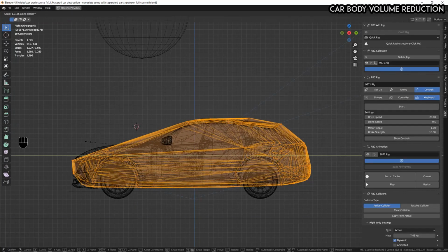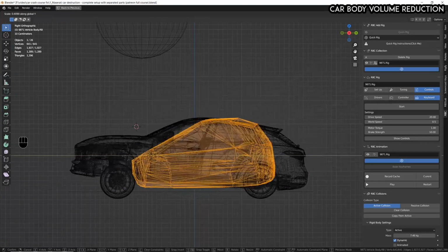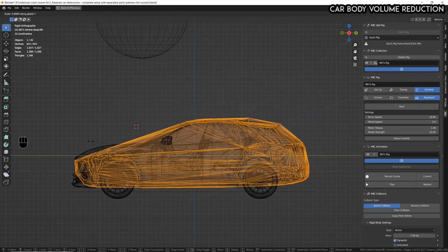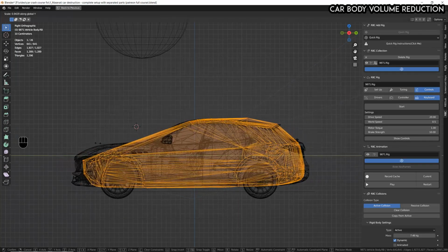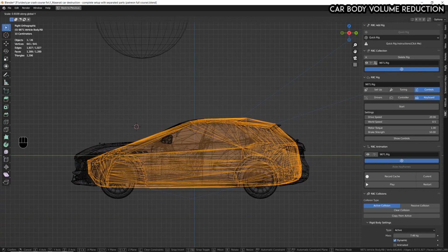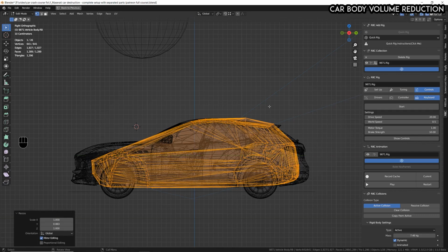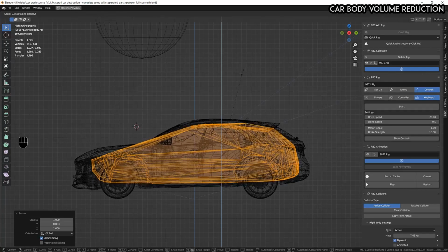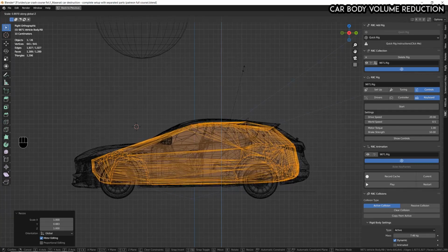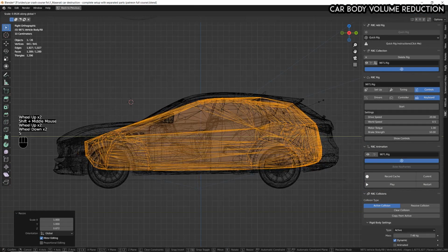Basically, I want to reduce the size of the rigid body a little bit like this. You will notice that the car is starting to rotate with all the parts as well. Don't worry about that, because once we scale also in the vertical direction, everything is gonna self-adjust automatically for you. So let's decrease the size until we create some space for the deformation in the front and also in the back. Something like, I would say, this is fine. Alright, now I'm gonna press S and Z to scale the vertical direction, like this, and you can see that the car is self-adjusting the rotation for you. Awesome. So just create a little bit of space around the borders, and you can see that finally I have enough space for the deformation. Let's see if I can push it a little bit more.